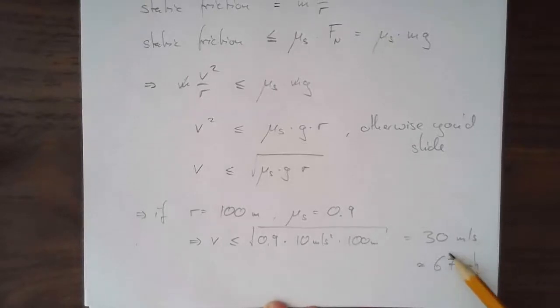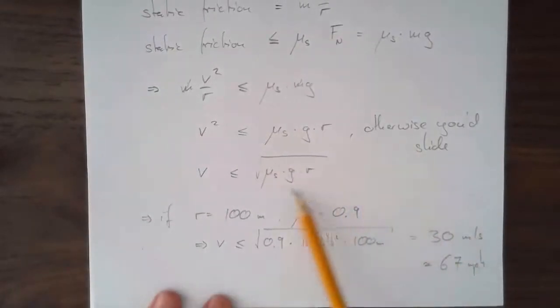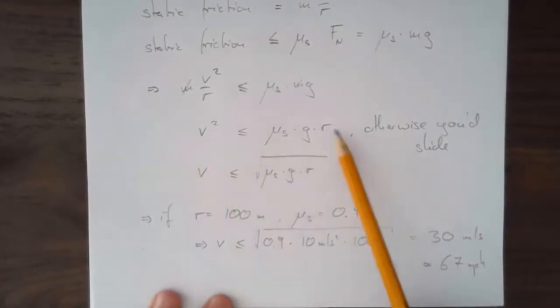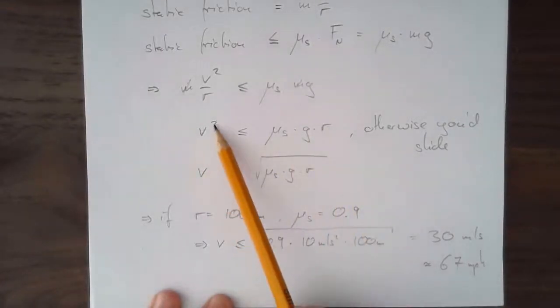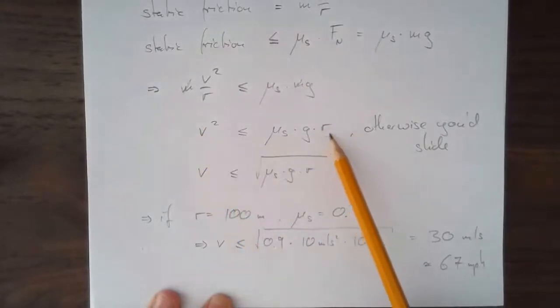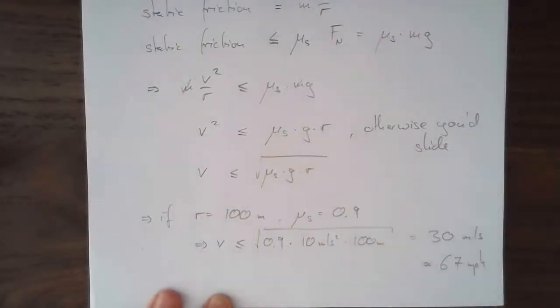And that's the kind of calculation an experienced driver kind of does in their head. You don't actually do the calculation, of course, but you sort of intuitively try to figure out how fast can I go around this turn. One thing that's interesting is that the maximum speed, like v squared, relates to r. So if I want to drive twice as fast, I need a curve that's 4 times as big to be able to do it without sliding.